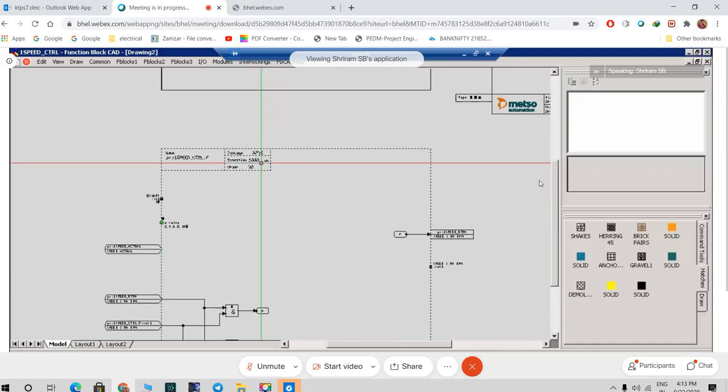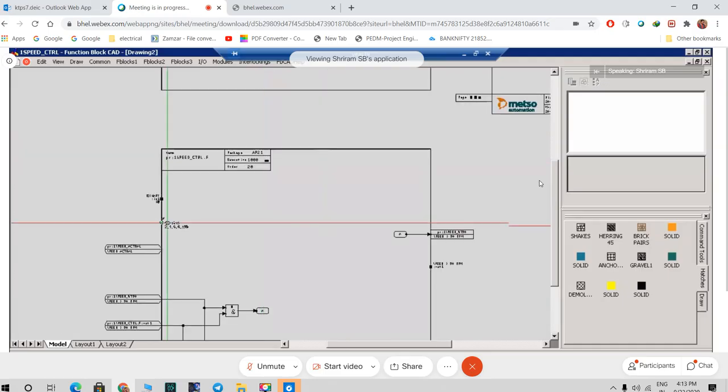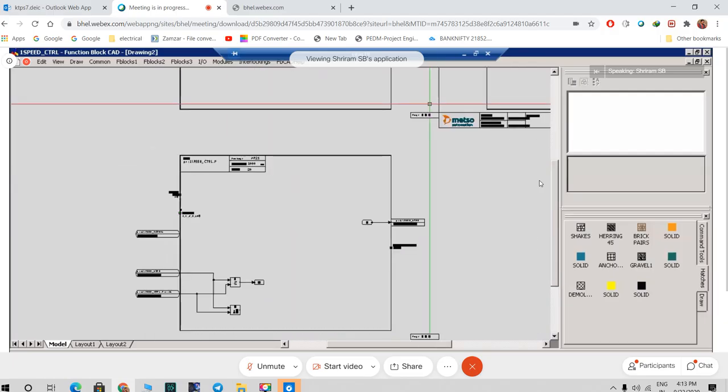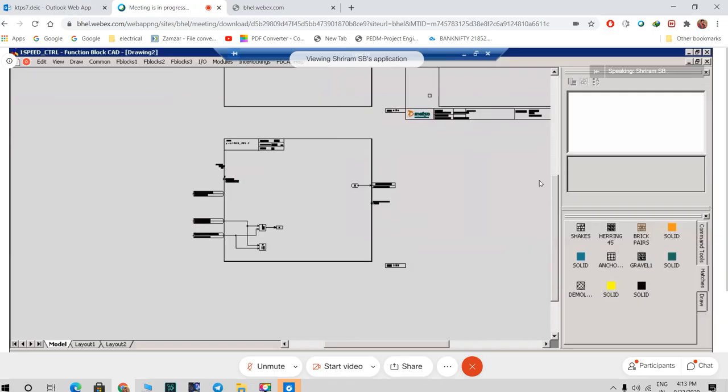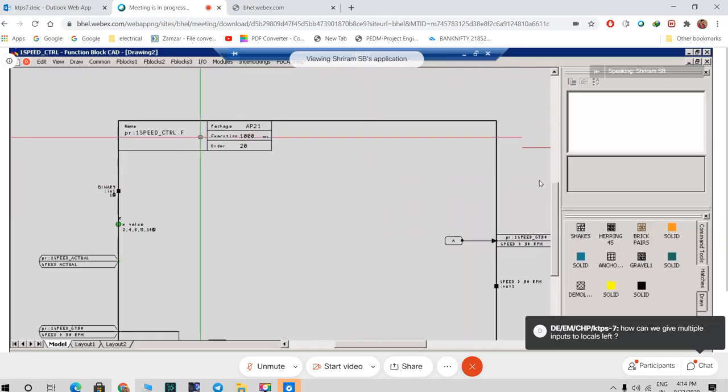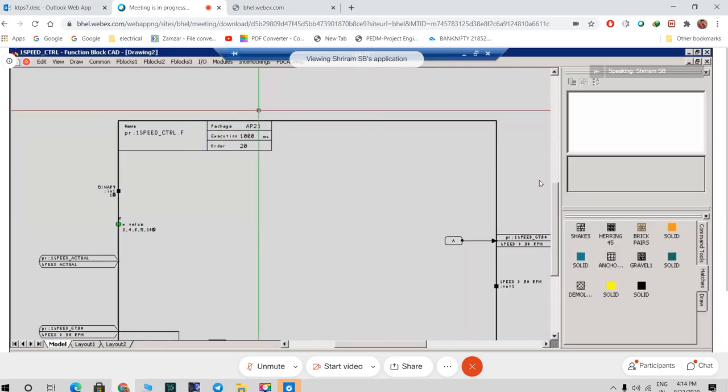So you cannot force the system to say, for page 1, see, suppose 1000 milliseconds is there here and we are having 3 pages. We cannot force the system and say the first page we should execute in 100 milliseconds, the second page in say 400 milliseconds and then the third page in 500, like that you cannot do. So the system will automatically configure the execution times of each and every block, but what it will ensure is that all the blocks present in these 3 pages will execute within 1000 milliseconds. That is the theory behind this execution interval for a particular loop.